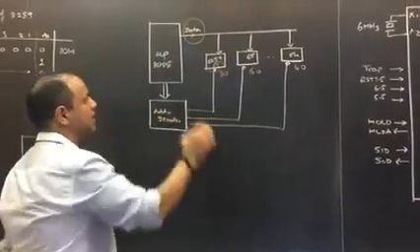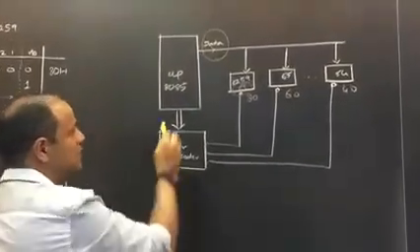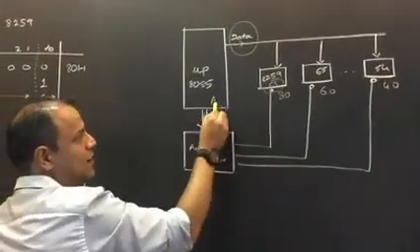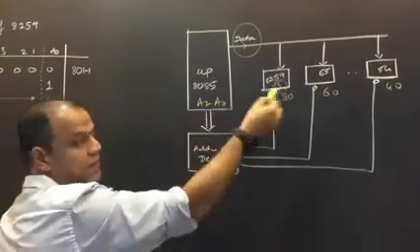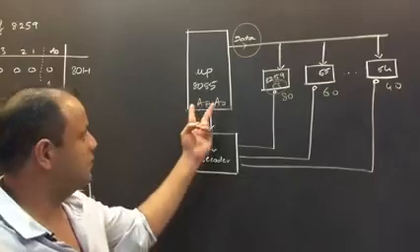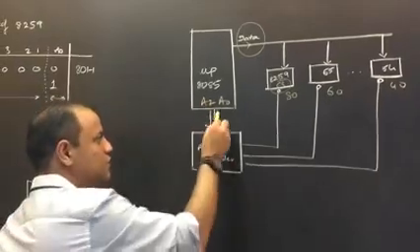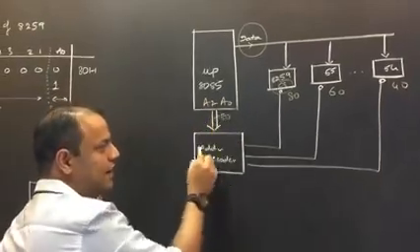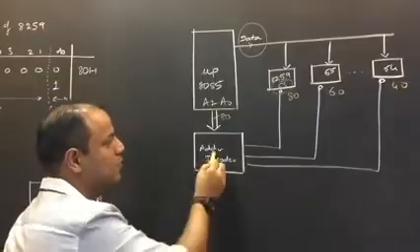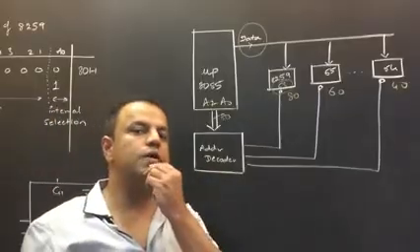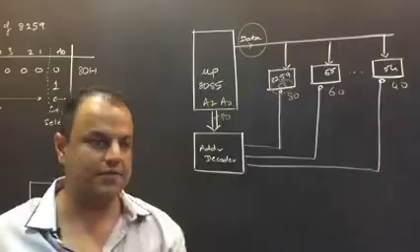So that's the idea. First T state processor will give the address. Now the address will come out on the address bus. Now since they are 8-bit addresses, it will be on an 8-bit address bus, that is A0 to A7. So let's say the address is 80. That address will be given to the address decoder. What will the decoder do? It will decode. What does that mean? Analyze the address.